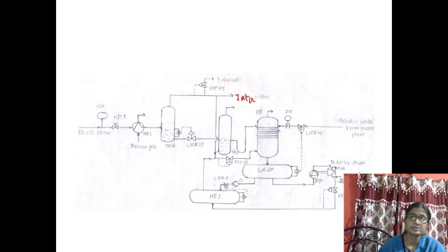So this deaeration process requires the polished water supply from the process plant, and high speed steam is flown from the bottom portion of the tank, so that the oxygen present in the water is carried out, and this is open to atmosphere.